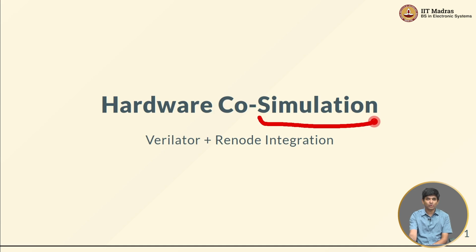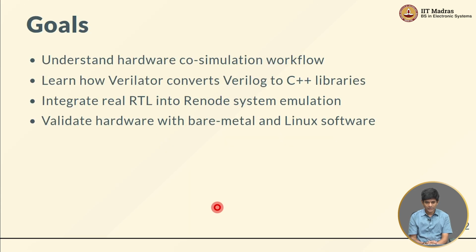For the most part, we don't want to get too bogged down in the terminology. As discussed earlier, Renode is generally thought of as a system level emulator. What Verilator does is Verilog simulation. It sort of literally is trying to go through the process of compiling the Verilog code down to an equivalent set of functions which can then be evaluated. Now, why would we want to do something of this sort? Let's look at that in a little bit more detail.